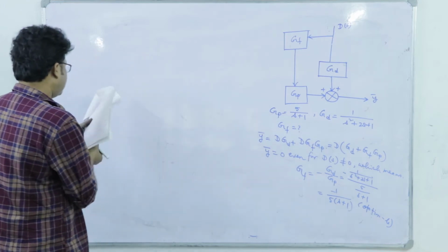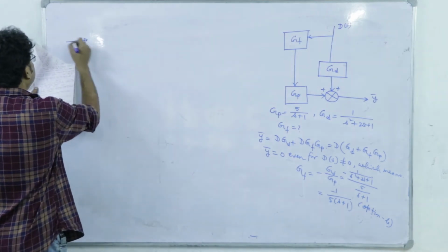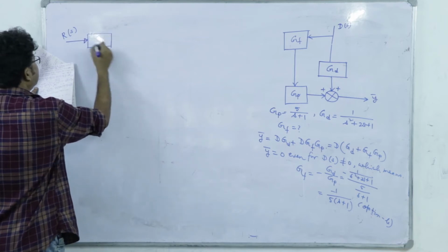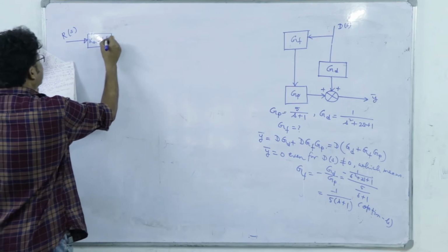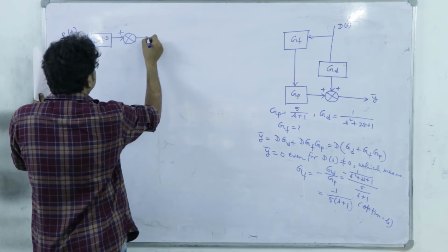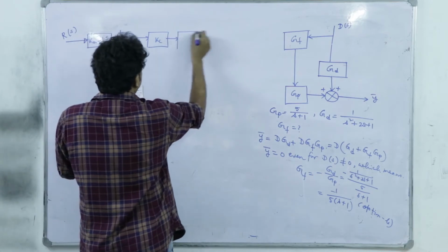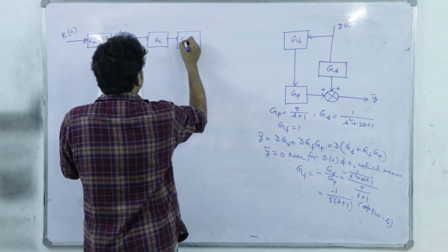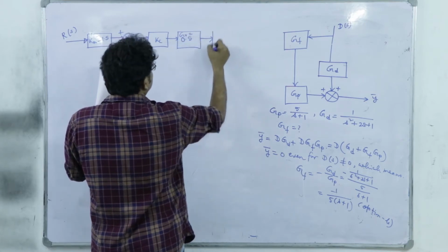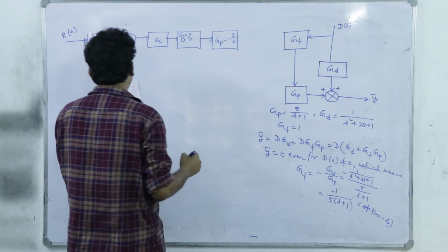Now, this problem is, we have a block diagram. Let us write that. RS, here this is a block with Km is equal to 1.5, then it goes to the comparator, this is Kc, this is 0.5, which is Gv, that is the valve basically. Next it goes to Gp, it's minus 2 by S, pure capacitive process.